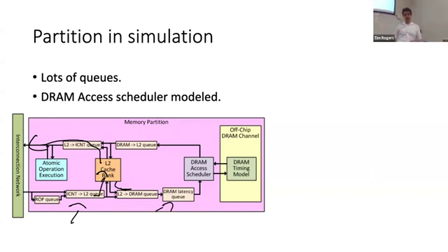And then in simulation, we have another latency queue because we try to figure out what the actual latency is to do these things. This is a bit of a software design decision to try to model how long these things actually take. So if you look at the code, it does look like this, and this is why, to just try to model latencies. Then eventually it'll go to the DRAM access scheduler, which will have different algorithms to decide, based on what's currently in flight, what I should schedule next. Then you'll send it out to the DRAM. DRAM will service it. The simulator you use has a model for DRAM, so it will model row buffer hits and this kind of thing. It is a variable latency DRAM system.